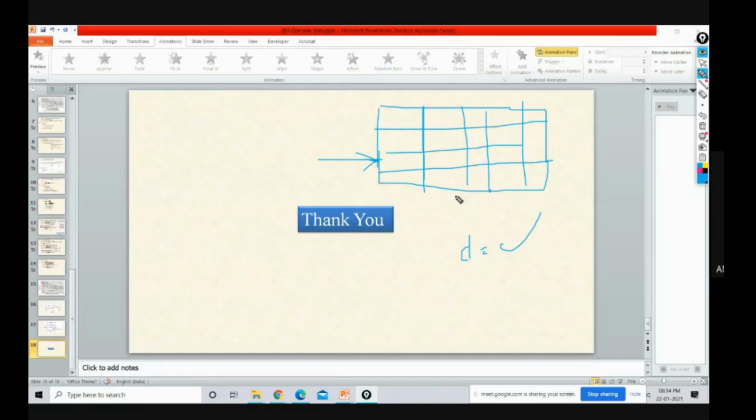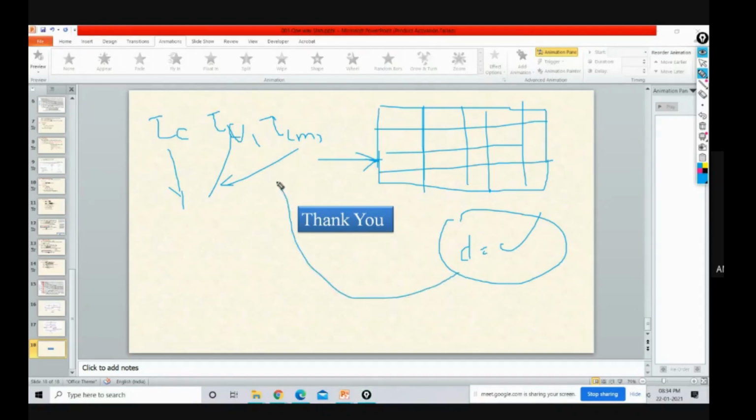How that shear reinforcement is required, we will see, because to decide whether shear reinforcement is required or not, we have to calculate tau v, tau c and tau c max: nominal shear stress, design shear stress, and maximum shear stress. Whatever stresses are produced in your beam or slab as per the depth will decide whether shear reinforcement is required or not.